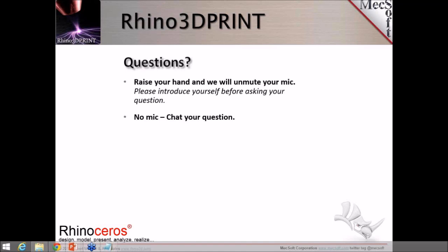One of the other big questions, Joe, was what operating systems are supported. Do you want to go over the system requirements for Rhino 3D Print? Yeah, we support Windows 7 and Windows 8.1. Actually, the product that Uday was running was on Windows 7. We have even run it on Windows XP, even though that's not a supported Windows. As far as resource requirements, we run on whatever Rhino requires. If you have that sort of box, you will be able to run our product. But it depends on the type of models you're working with. If you're working with large models, you definitely want to increase your RAM as well as your processor speed.